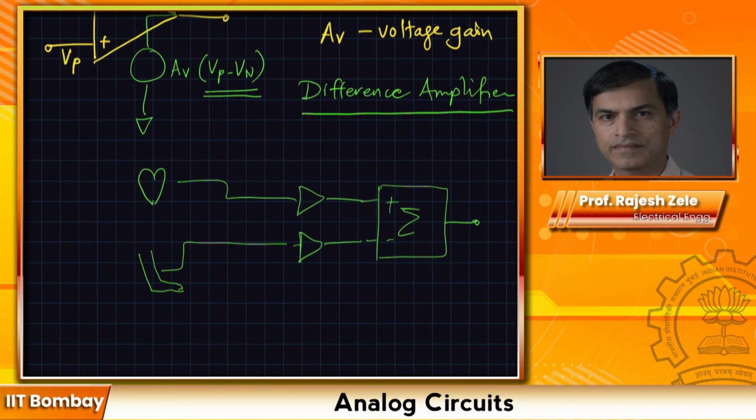Let's say we connect one lead towards the heart and one lead towards your leg. I'm sure all of you have played with an oscilloscope before and touched the lead of the oscilloscope. If you touch the lead, you will see a really large signal. If you keep playing with it, you will see a 50 hertz or 60 hertz tone, depending upon which country you are in. That's a pretty large signal riding in your body all the time, because of the surroundings you are in.